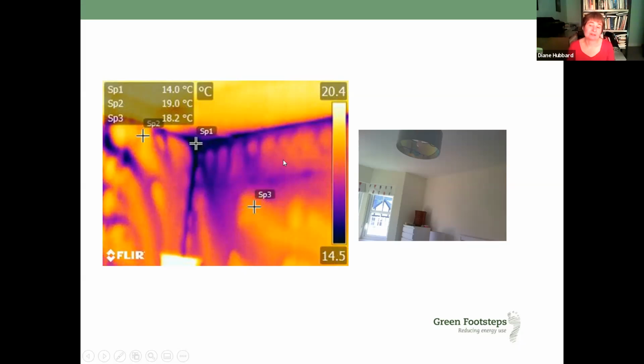So in this case, we're not only looking at the insulation being bypassed, but we're also looking at risk of mold growth as well. And one of the things when we're looking at retrofit is that quite often dot and dab plasterboard is something that's commonly used. It's routinely used in new build, and the impact of it just doesn't seem to be appreciated.